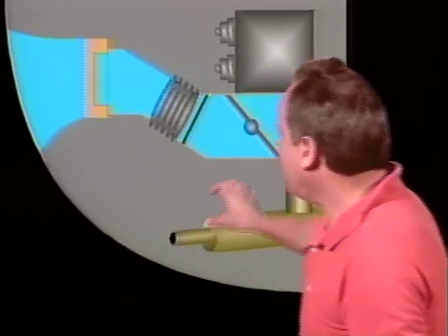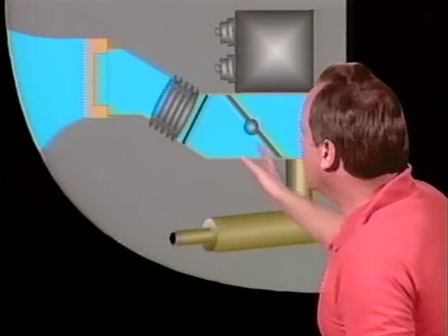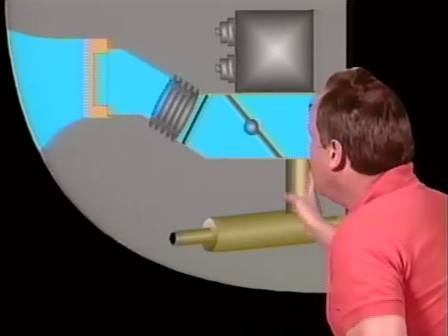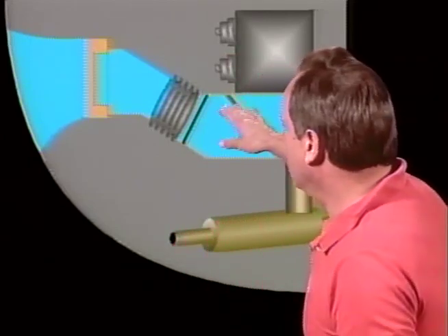And they're going to say, all right, let's assume that a pilot comes and says, oh, look, I'm not getting full power on takeoff. What could be one of the problems? And the answer is the linkage here in the carburetor heat valve, this butterfly valve, could be allowing carburetor heat to be heating the intake of the engine on takeoff. So a factor in the failure of an engine to develop full power at takeoff could be due to improper adjustment of carburetor heat valve control linkage.